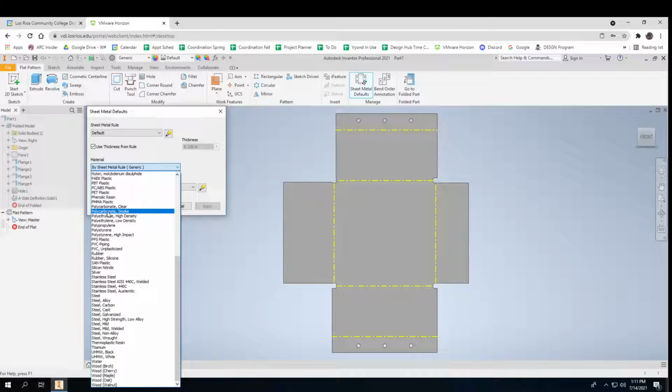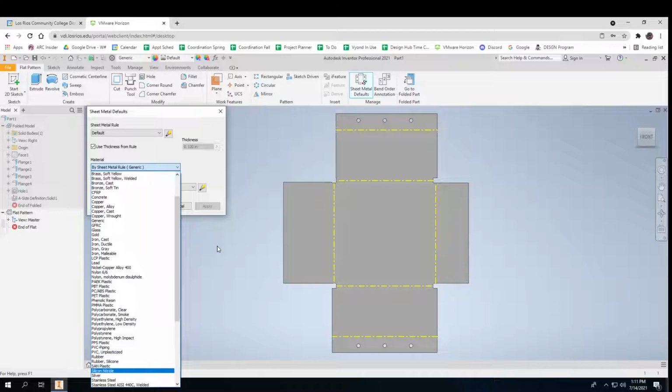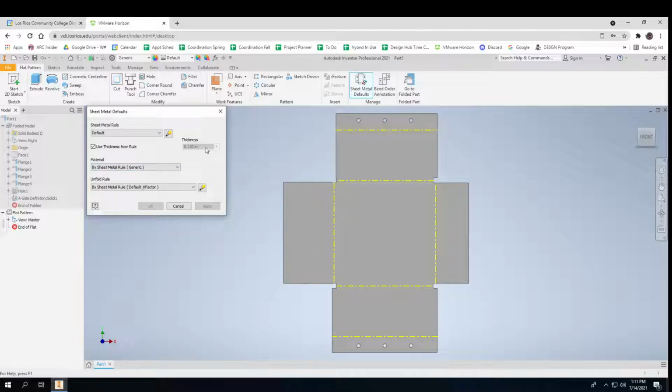I've done that before. So it sort of gives you this whole material list, but you've got to apply it in a way that you know how these things are happening. Like, what are the bend radiuses and what are you going to unfold and how are you going to set these thicknesses? So it really is for bendable stuff.